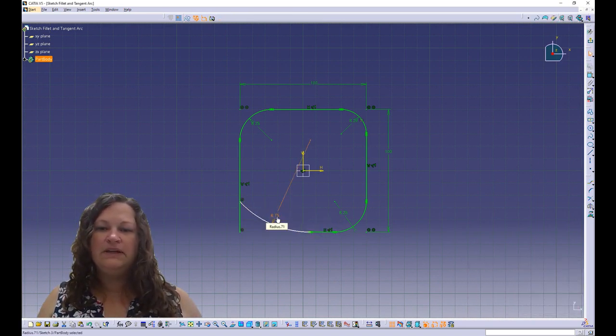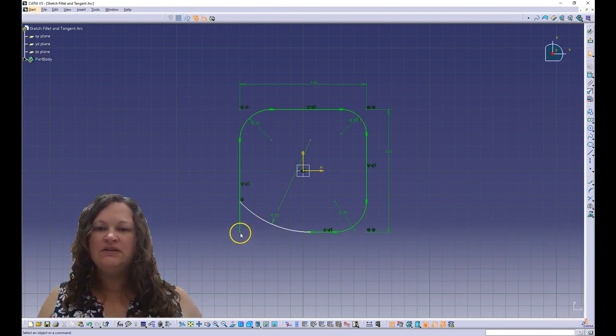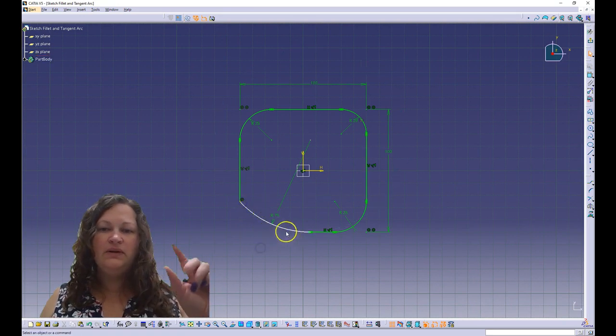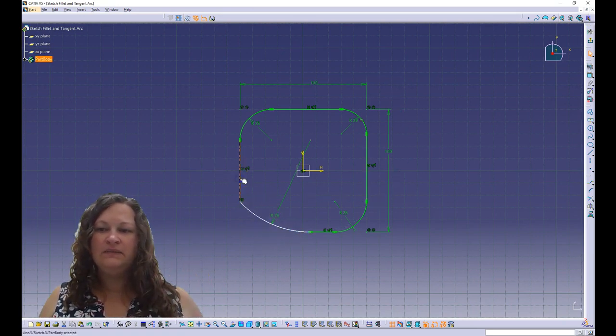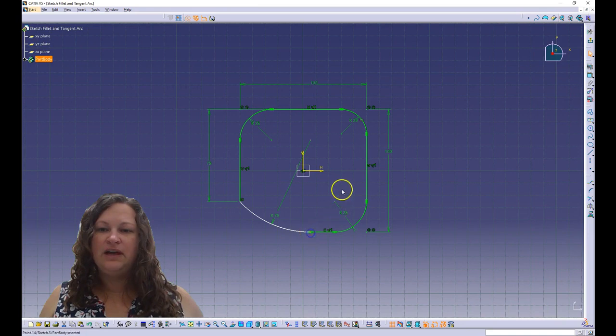But when you place those, you want to make those coincident. It looks like I actually missed it right there. So when I add the measurement values to the length, as well as on the horizontal, it actually goes through and fully constrains the sketch. But what it does is actually leaves a little bit of an open gap over there in that corner that I modified.